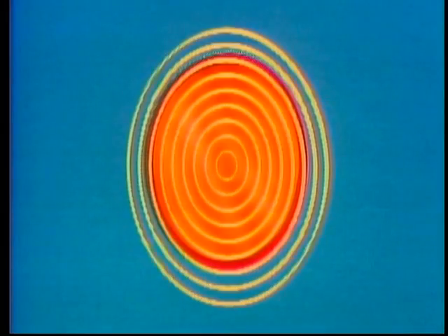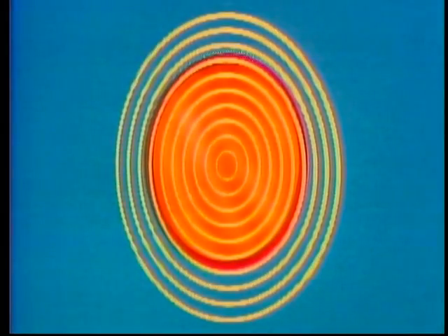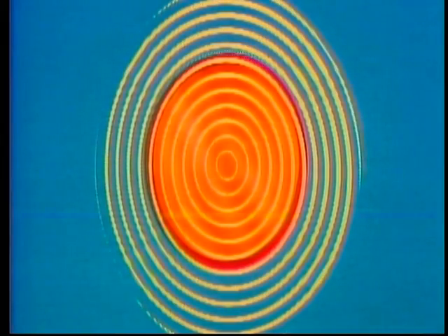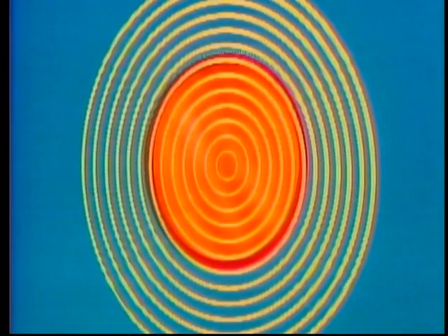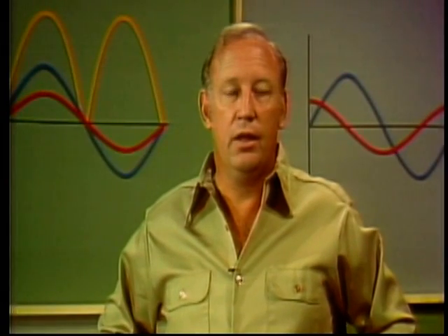An instant later, the field is still building up. There are more magnetic lines now, and some of them have expanded around the outside of the wire. Each one of these lines started at the center of the wire and cut through all or part of the wire to reach its present position. Another instant later, the magnetic field has still more lines, and most of the lines have cut through the wire. The magnetic field will not build up any further because the current that's producing it has reached its peak positive value. Let's stop here for a minute and review what has happened.